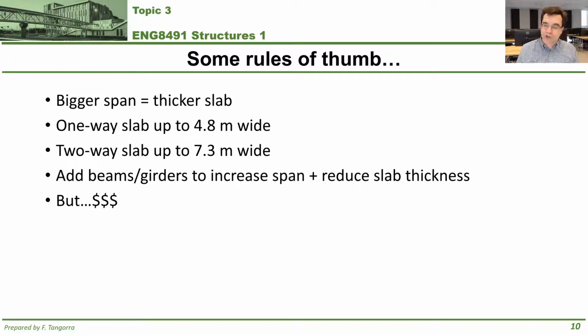Because with reinforced concrete, you pay for the shaping of the structure, the forming, you pay for the reinforcing, and you pay for the human labor time associated with that. The expensive part in reinforced concrete structures is typically considered the forming, because it's usually custom.